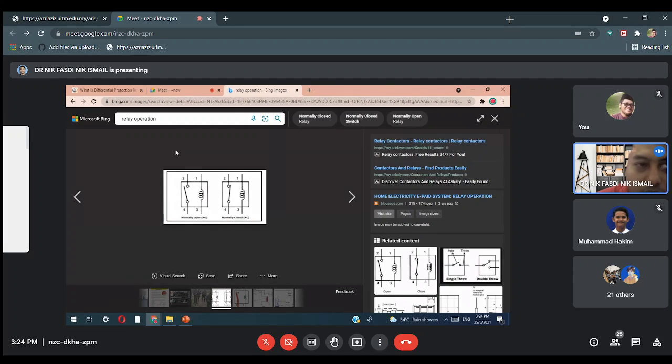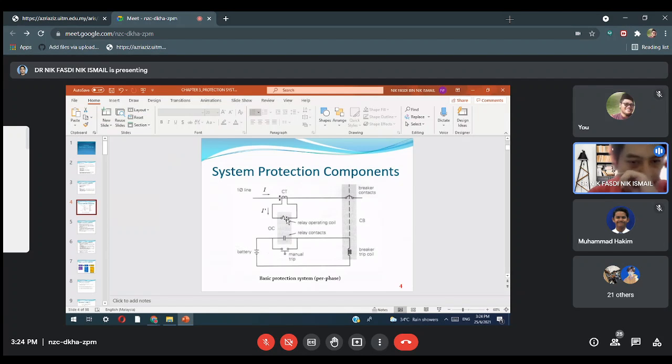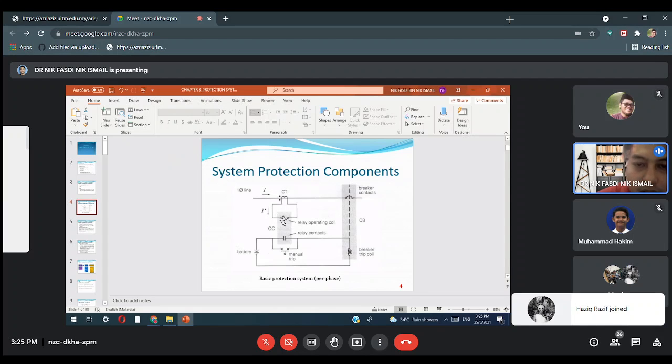That is the concept. If you go back to the note here, this is the concept. You must understand the concept of the relay. Okay. So the contact is on the coil. Whenever I prime is greater than pickup, and the overcurrent relay has something called the pickup current, whatever this I secondary current of the current transformer is, if it is greater than the pickup current, it will energize and turn on the coil.